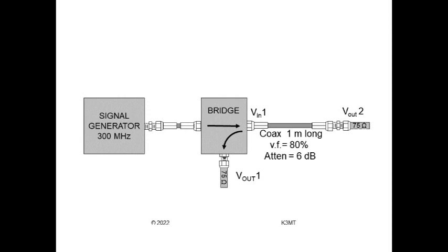So, to wrap things up, measure the S parameters by terminating every port but one in the proper load resistance. Drive the remaining port through an RF bridge. Measure the voltage out of each port, and that received back from the bridge. Divide each by the voltage driven from the bridge into the input port. Don't forget the phase delays. These ratios are the network's S parameters. It's really quite that simple.